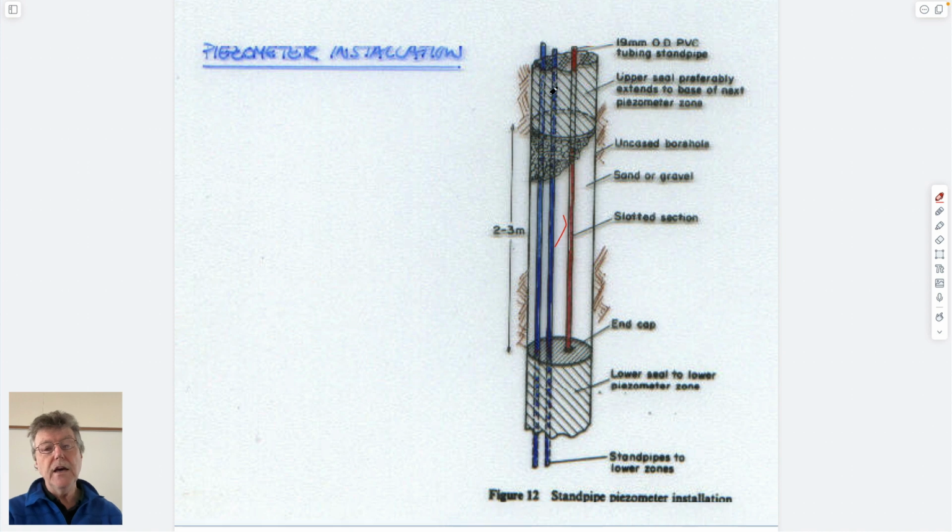So this way, now you have a whole bunch of these individual piezometers, a piezometer nest. Each of these zones is isolated. You could run a slug test in each of these holes to measure permeabilities, and you can also sample the pressures at the surface by how far the water level rises in each of these, using one of those little probes, and you can measure it over time to see what's going on in your system.